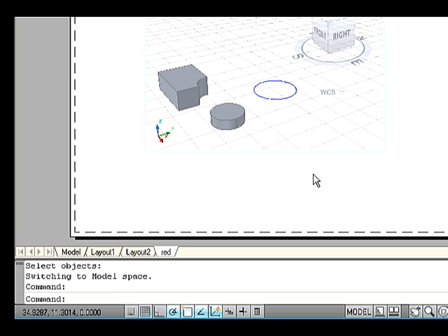Object. This specifies a closed polyline, ellipse, spline, region, or circle to convert into a viewport. The polyline you specify must be closed and contain at least 3 vertices. It can be self-intersecting, and it can contain an arc as well as line segments. With the Object option, you can select a closed object, such as a circle or closed polyline created in paper space to convert into a layout viewport. The object that defines the viewport boundary is associated with the viewport after the viewport is created.